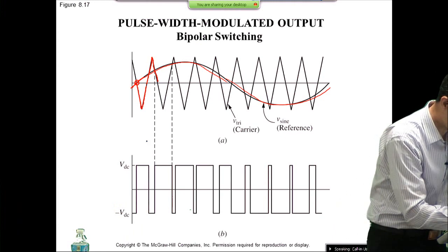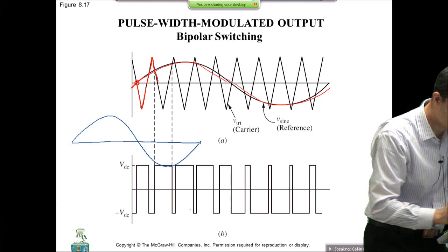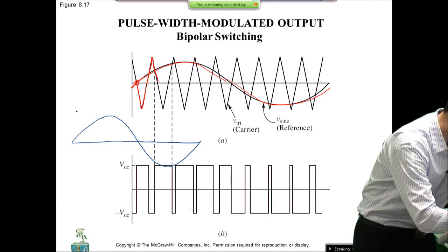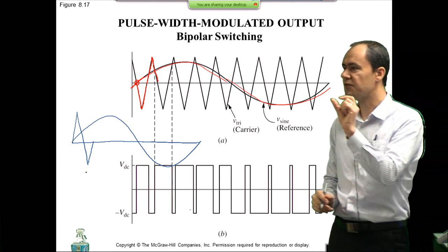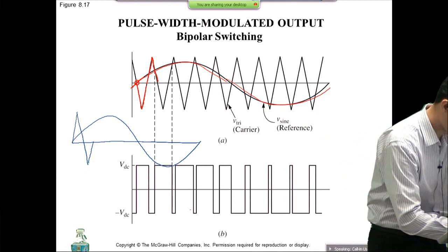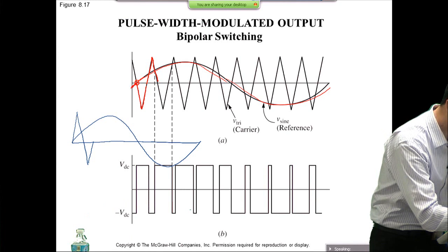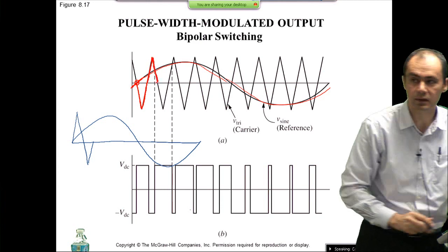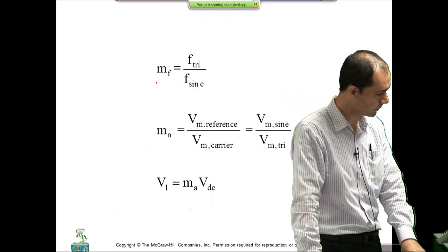So if you do it this way, you are probably going to get into some troubles. So let's say this is your carrier, and this is your triangular. In terms of the phase between your triangular and your sinusoidal, whenever you are crossing zero, like over here, your triangular first goes to the negative areas, then goes to the positive areas. So just keep that in mind in case you're implementing this, because you may actually face some troubles.